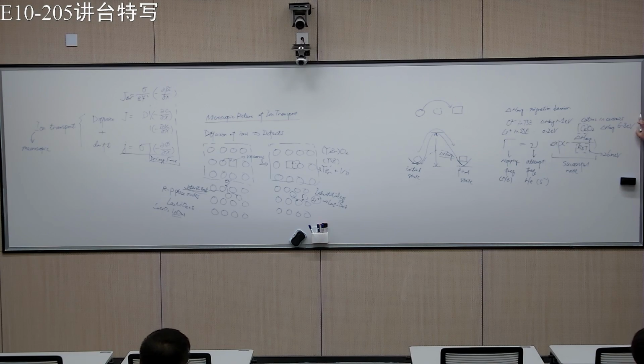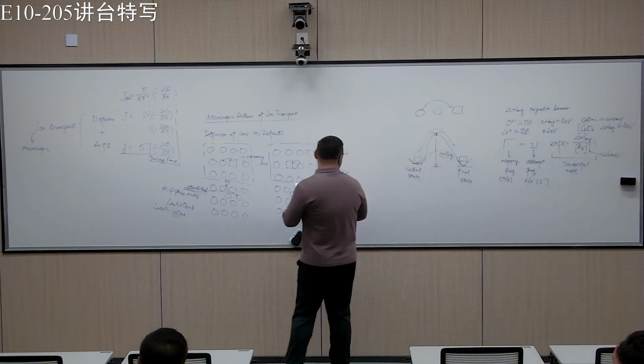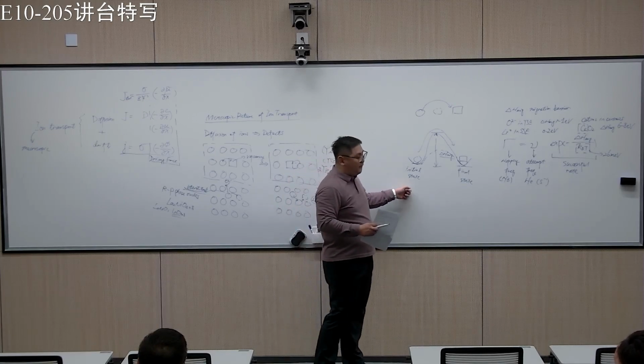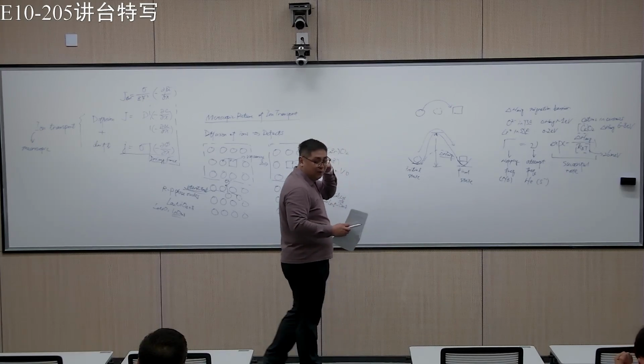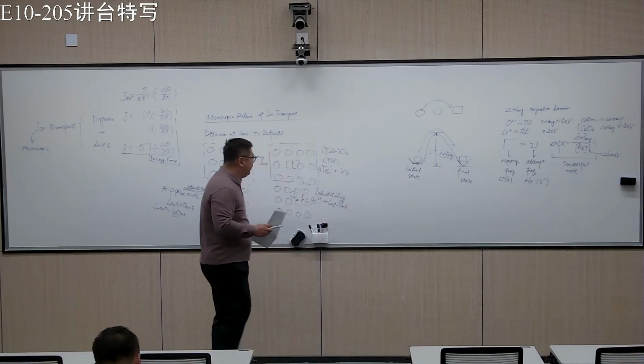Now usually cation migration is really difficult, and that's why if you sinter a ceramic sample, you have to go to very high temperature, something like 1200 degrees C, or even 1400 degrees C in extreme cases. All right, so this is basically the picture we use to microscopically understand the diffusion of ions.